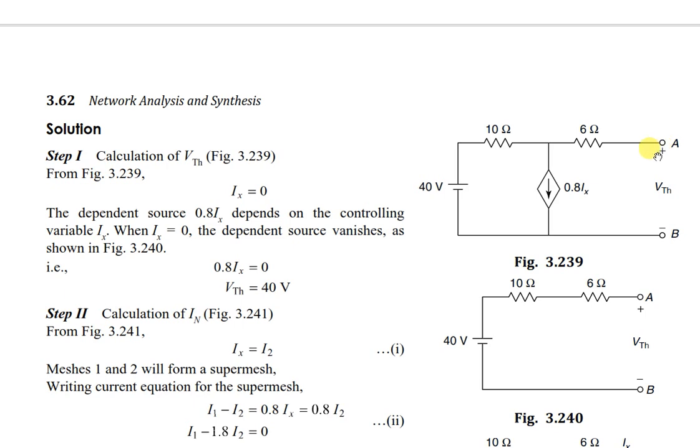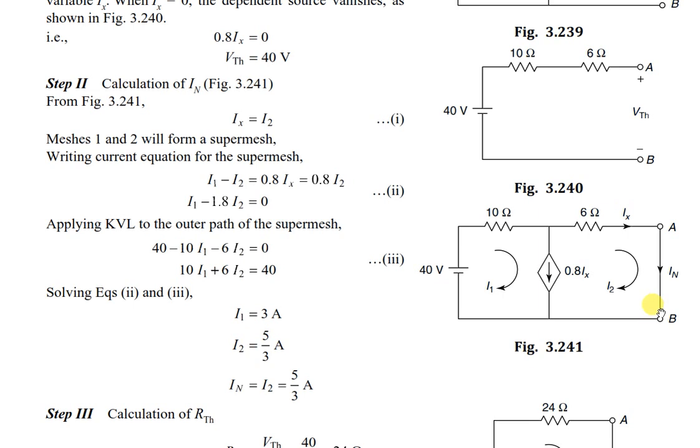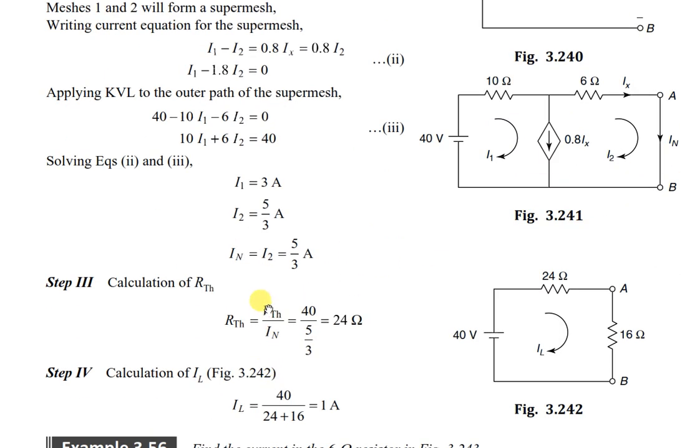So for this problem, just remember, for any problem related to dependent sources, you have to identify the load, and you have to find open circuit voltage across it using any technique, find short circuit current across it using any technique, and RTH is found out by open circuit voltage by short circuit current. If it is Thevenin's theorem, replace with the Thevenin circuit. If it is Norton's theorem, replace with IN in parallel with RN, connect RL once again, and using current division, you have to calculate the current in Norton's theorem. Using this simple equation, you can find the current in the Thevenin's equivalent circuit.